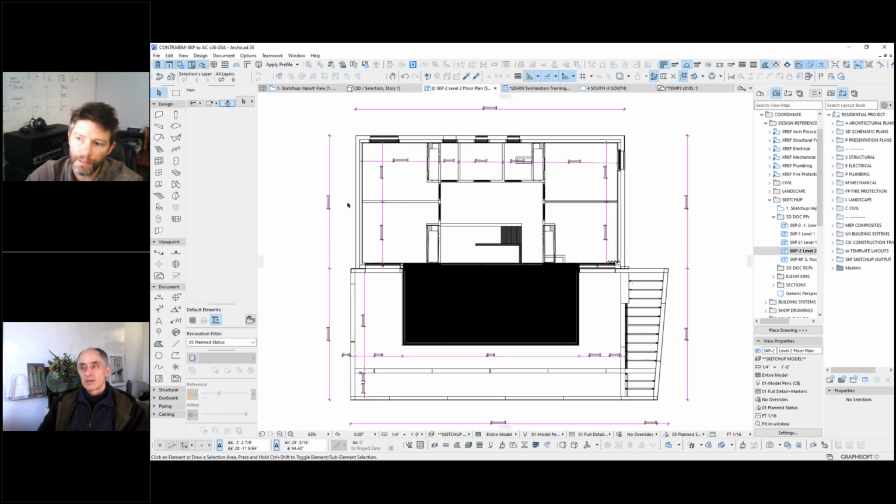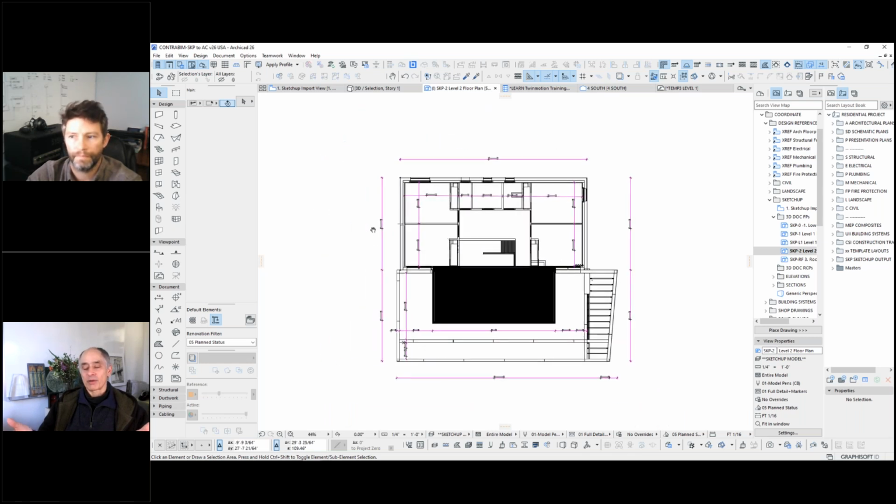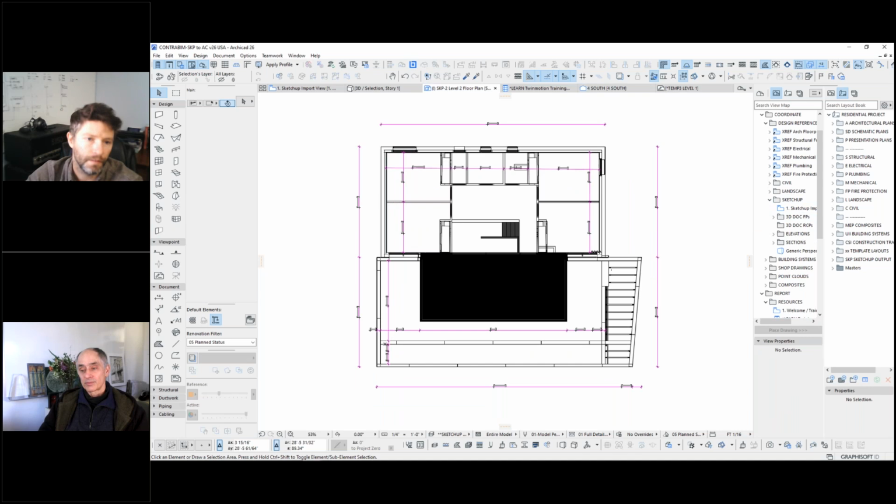Okay. And now this is a 3D document that is linked to the SketchUp model. Now you can't actually drag the SketchUp walls around unless you turn them into a morph or something like that, and that probably is more headache than it's worth. So you're now using that as a trace reference for drawing walls? Yeah, essentially. So in this workflow, generally you bring in the SketchUp object.